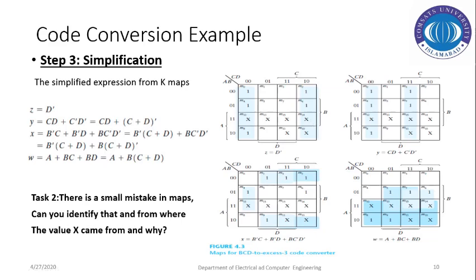So here the pairing depicts that we've considered the x as 1 because we are making the pairs depending upon the min terms. If we see the pairs that have been constructed here while representing the expression for z, it's a group of 8 cells, and the term which is not changing within the group in all the 8 cells is basically the d in its complemented form.